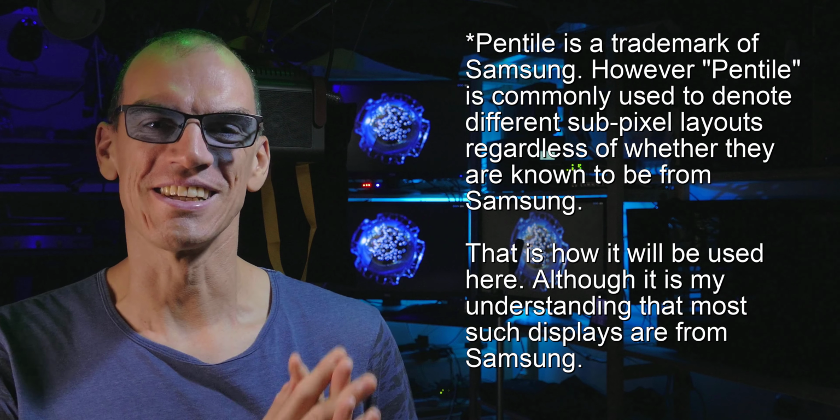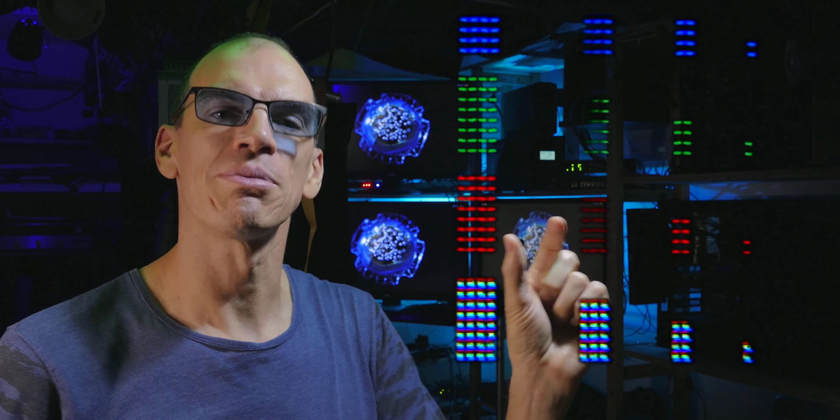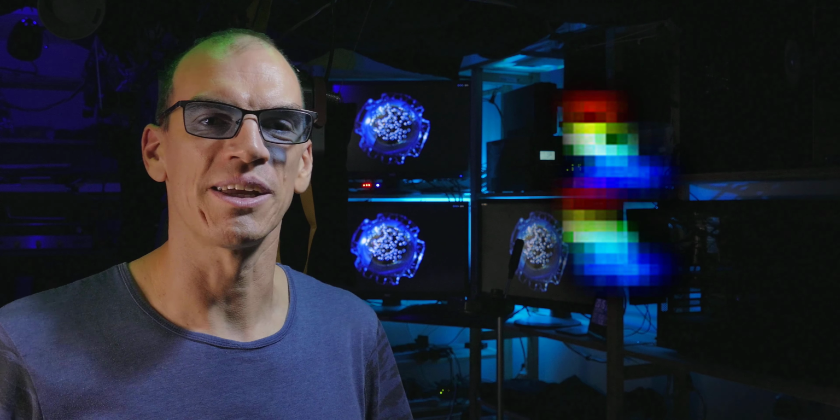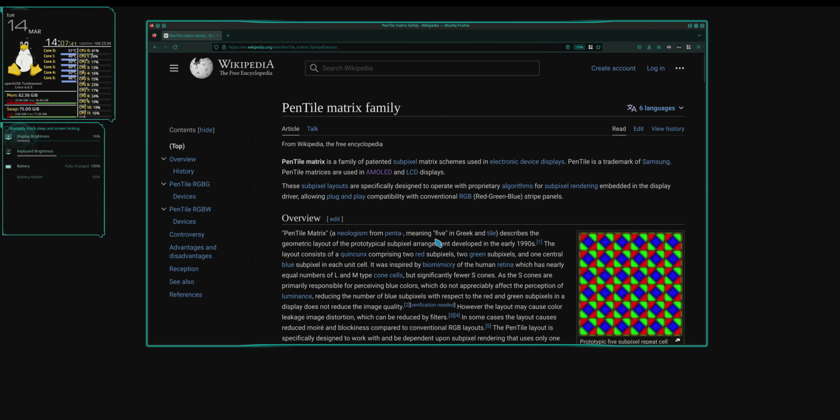Okay, so at this point we need to discuss pentile displays. If we have a look at what we think of as a traditional RGB display, you have the red, green and blue, and they're all very closely related to each other. You have one complete set per pixel. So if you have a pixel over there, it's got a red, a green and a blue. And you have a look at a pixel over here, and it's got a red, green and blue. And that's all fine. Pentile displays share some of those elements. And that comes with a whole heap of advantages and disadvantages. So we probably need to dive into that a little bit now. The first thing that surprised me about pentile displays is that I thought they were a fairly niche thing.